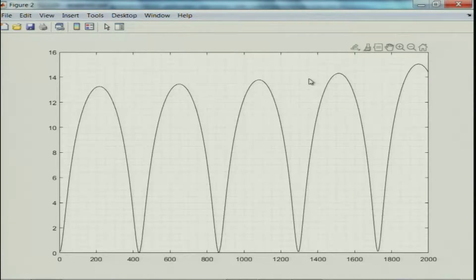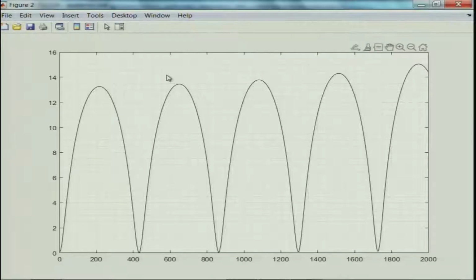However, I must point out that the transmission loss performance of an ECTR, that is extended concentric tube resonator, will be quite different in terms of tuning of the length compared to a simple expansion chamber with neck extensions, for the simple reason that perforate impedance has a major role to play. And you notice in the slide, the transmission loss is not identically 0, although it tends to that; practically it is 0, but there are troughs that are lifted.